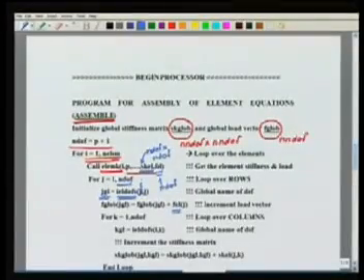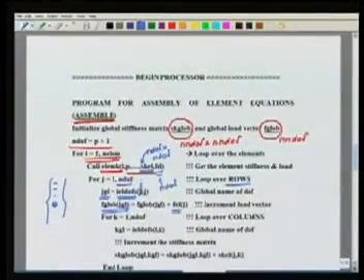Then we have obtained the element level load vector. So we take the corresponding global load vector entry, that is given by JGL. To this entry I now add the element entry. There is a one-to-one correspondence between j and JGL, through which I add this element entry to the global entry. So essentially I am looping over the global rows, and to them I am adding the local rows in the right positions. This is for the load vector.